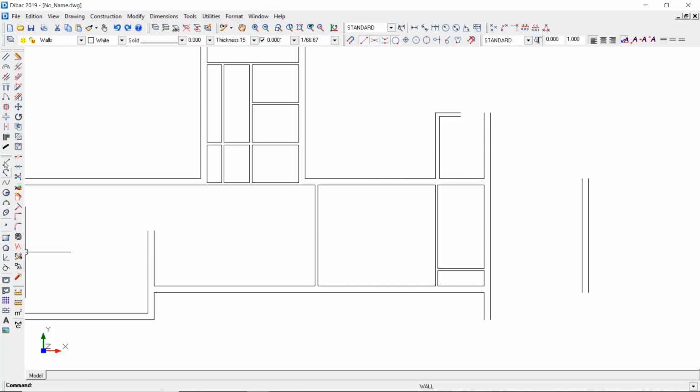After finishing all the walls, I can use the Line tool to close the walls without corners that remain open. Every time you create a line, make sure to double right click to exit the function and restart the function quickly.